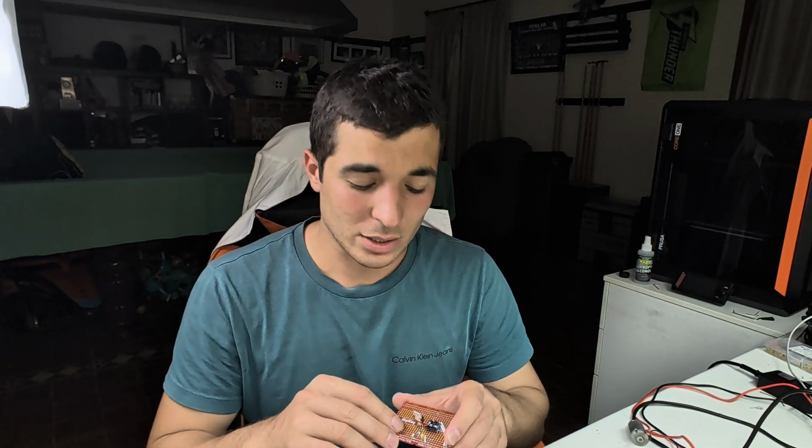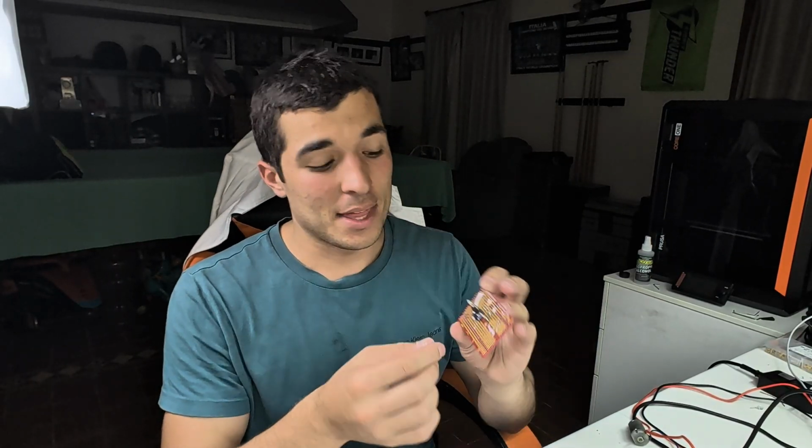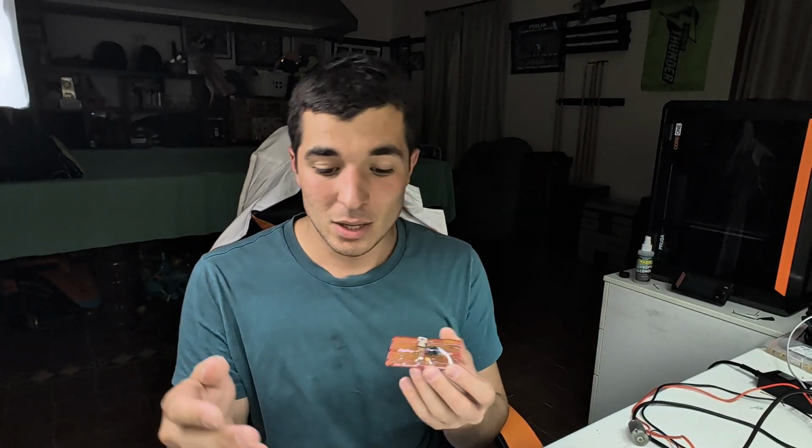So it wasn't actually working, and it was because of that pin that wasn't connected. It was the out low that wasn't connected. I had to take this off and test it separately, which is why I went through so many boards, only to realize that it wasn't soldered on properly.